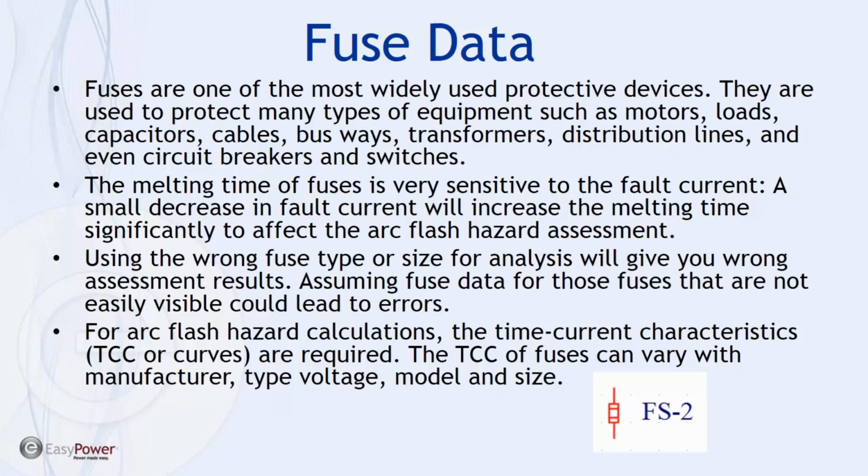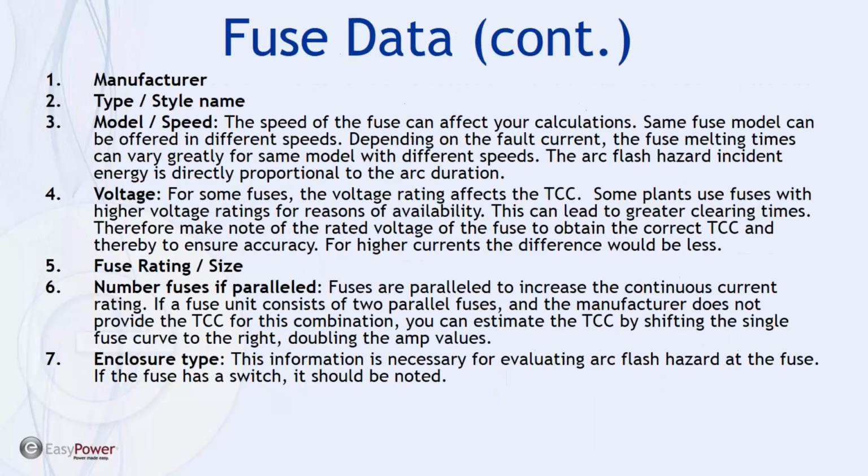A good point to be made here is anytime we're looking at fuses, make sure all the phase fuses are the same, and that you don't have multiple values or different values on each phase. Again, when you get into the calculation mode or whenever a calculation is made, you utilize the worst case situation, and if you have one fuse that's out of whack, that could skew your results considerably.